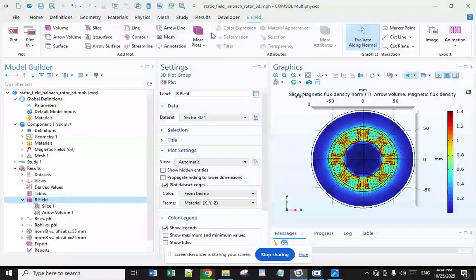For instance, between sealed containers or pressurized vessels, the optimal torque coupling consists of a pair of coaxially nested cylinders with opposite positive core and negative core flux magnetization patterns, as this configuration is the only system for indefinitely long cylinders that produces a torque.